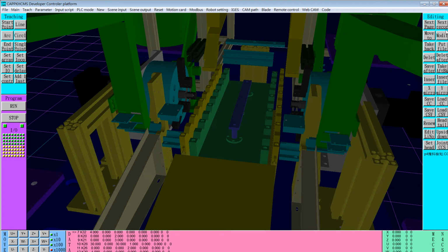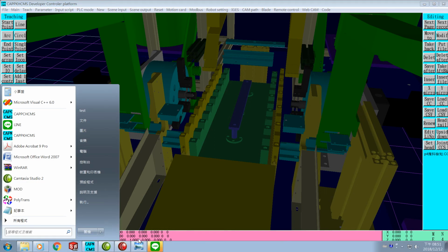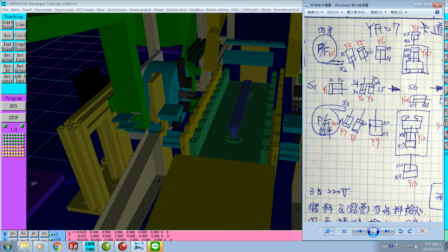After waiting for 3 and 4, then we will let this one drop in here, waiting for inner tapping piece assembly. How to let this one drop? First, we have to activate Y2 cutting plate, isolate the single one here, and then retract Y3.